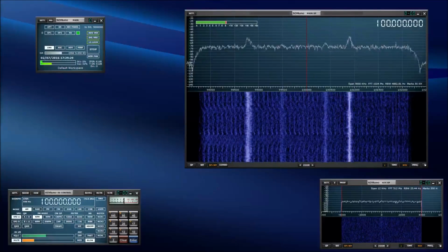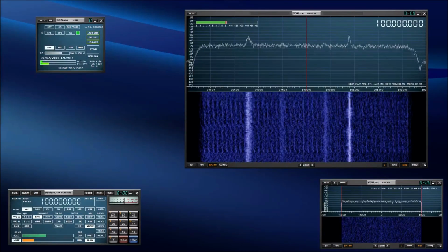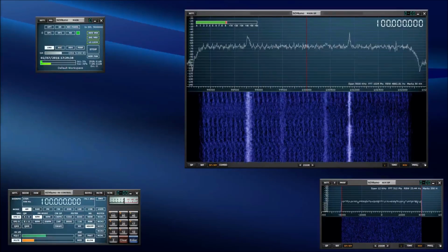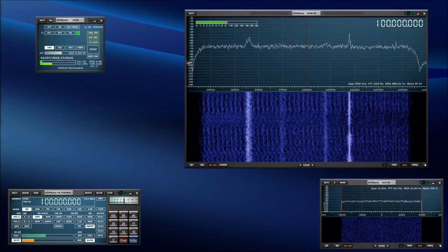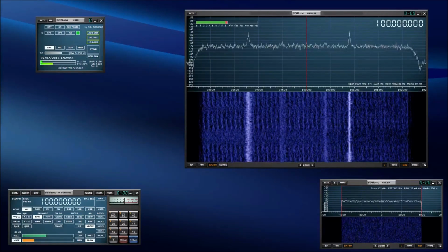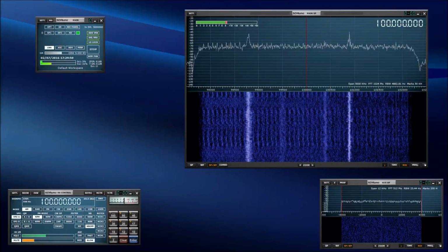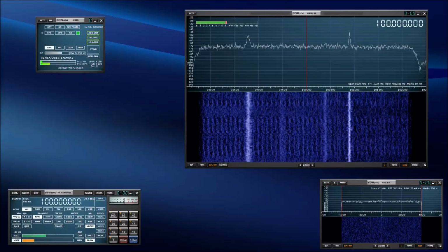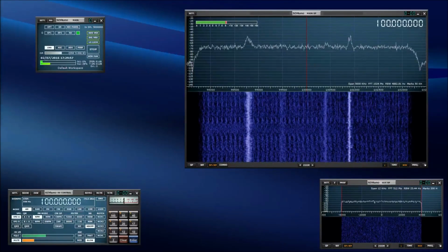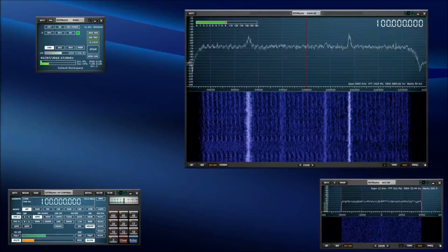Okay, so gain is an analog measurement of signal amplification between defined points, and the only defined point within the RSP is the antenna port. So you cannot do an absolute measurement of gain. Even if you consider the ADC input to be the output of the analog signal chain, the absolute maximum gain from the antenna port to the ADC input varies from band to band.